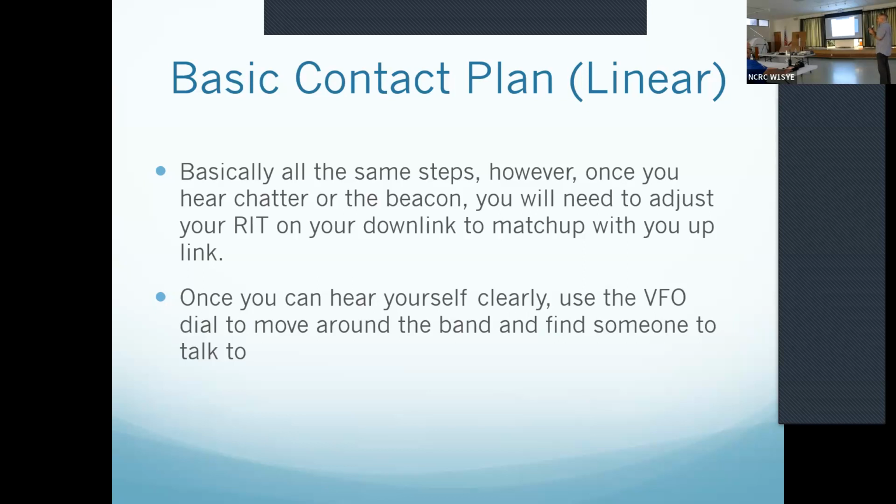So you're going to transmit up on the frequency, and because that band is so wide, you're going to start calling CQ to yourself, like CQ satellite, KC1 and AM, and then you're going to be moving. I move the RIT, and I'll move the RIT, and then all of a sudden I'll see myself on the waterfall, but I'll sound like, when somebody's 1,000 kilohertz off frequency, like a monster. So then I'll just start tuning the RIT slowly, and then I'll hear myself until I sound like myself.